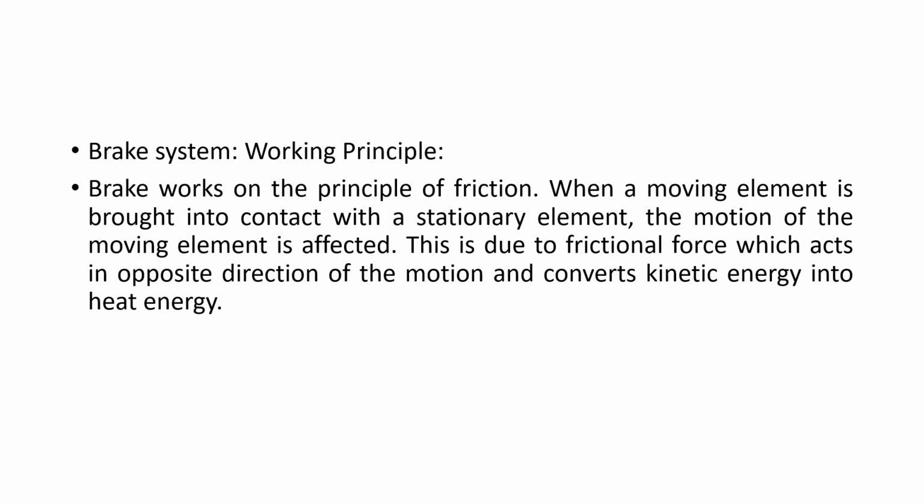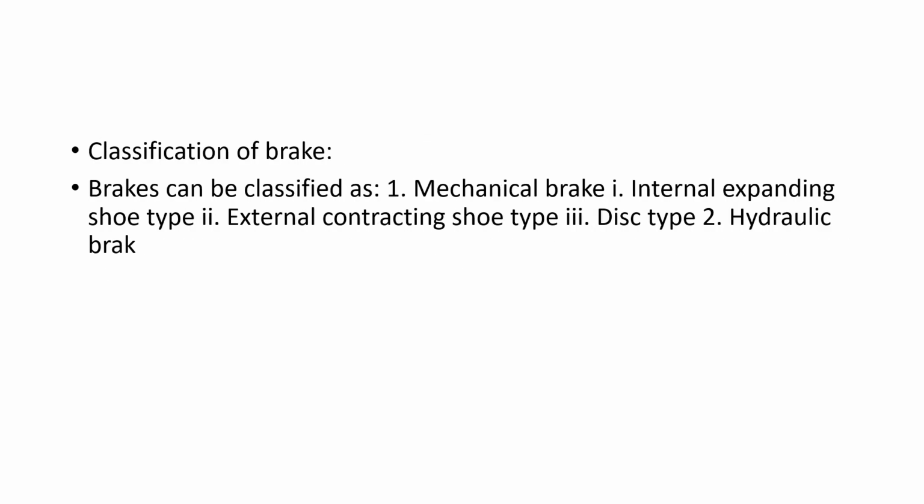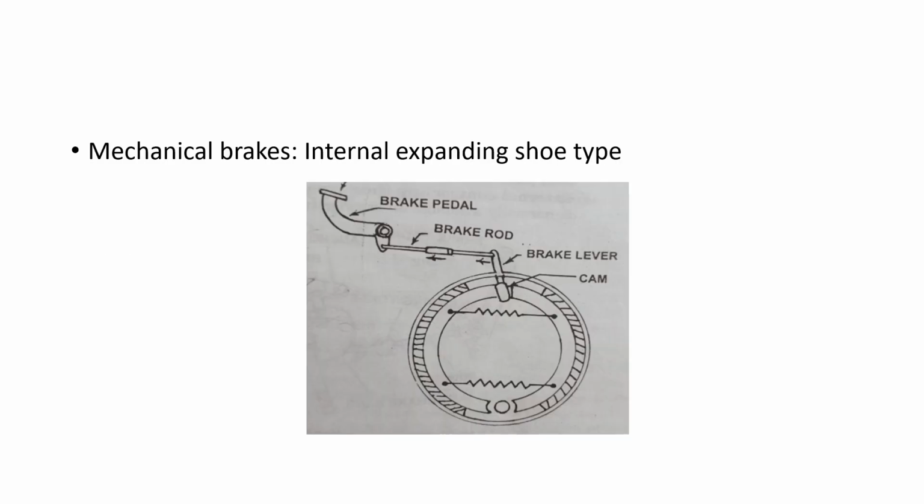Again, when a moving element is in contact with the stationary element, the motion of the moving element is affected due to the frictional force. The magnitude of the frictional force depends upon the type and quality of the surfaces in contact. We have different classifications of brake systems: mechanical brakes, which can be the internal expanding shoe type or the external contracting type, and also the hydraulic type.